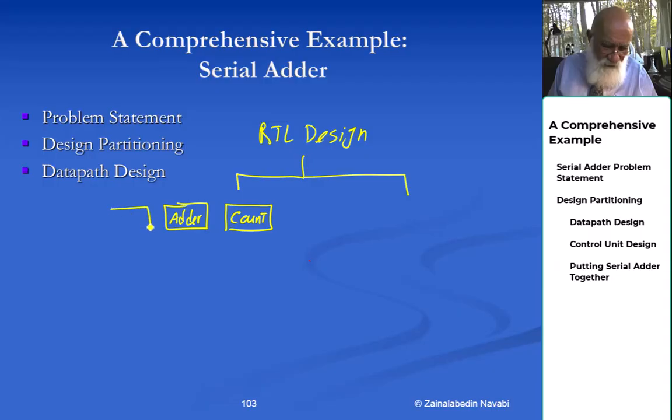What is a register file? A register file is really a short memory. As you are deciding all of this, you are saying, well, the counter has to count when I tell it to, and also it has to reset when I tell it to. The adder sometimes adds, sometimes subtracts. The register file sometimes is written into, sometimes is read from. All of these red ones I'm marking become your control signals.